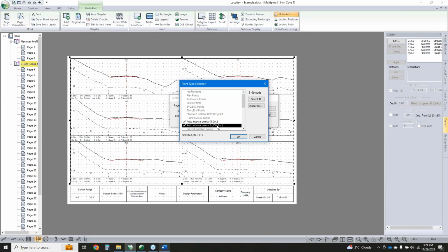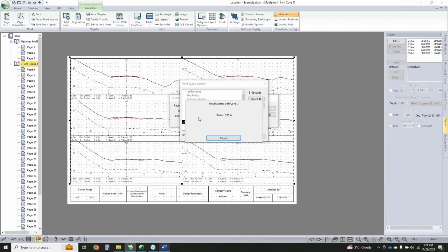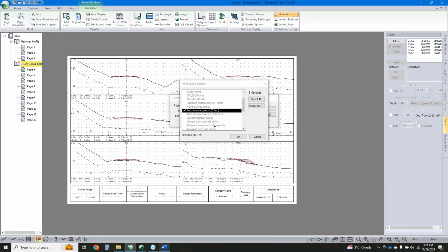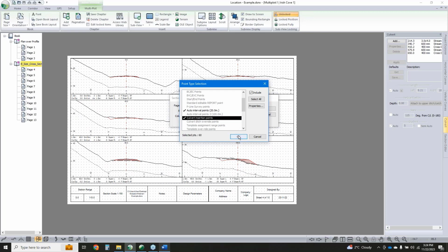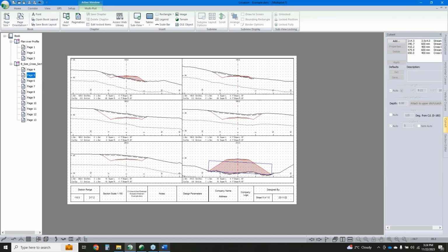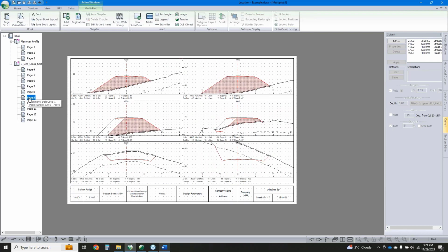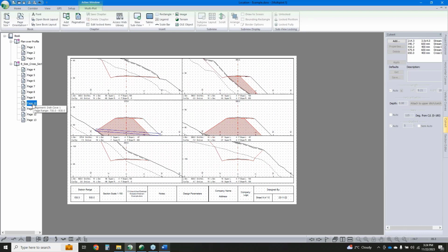Let's change this to be every 20 meters and everywhere that we've added a pipe. So 0, 20, etc. And then at 214.3, we've got our pipe arch that lands at an odd value. And we can continue along and we see what we're dealing with.